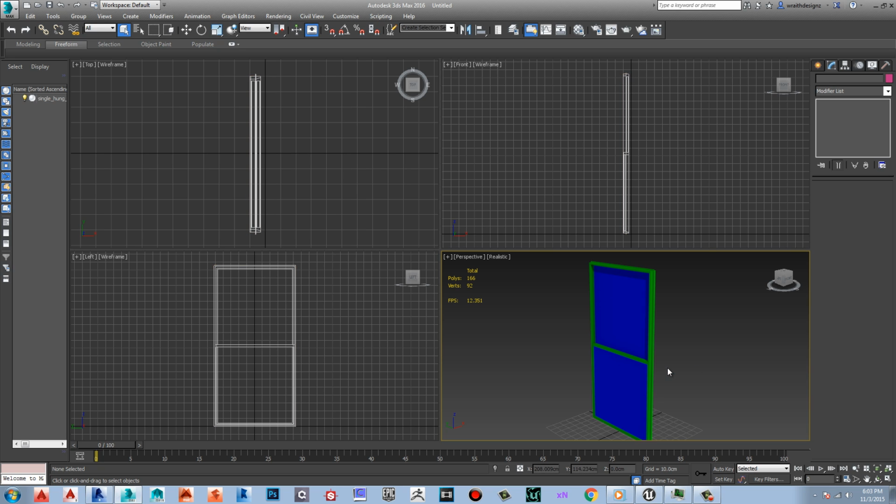So anyway, as you can see here, I used green for the outline, blue for the windows. It doesn't really matter what you use for colors or materials. What matters is that it just embeds in the 3D model data that once it's imported into Unreal Engine 4, it will tell it has 2 slots because there's 2 different colors on the model. If you kept it 1 color, you'd have 1 slot. So just keep that in mind.